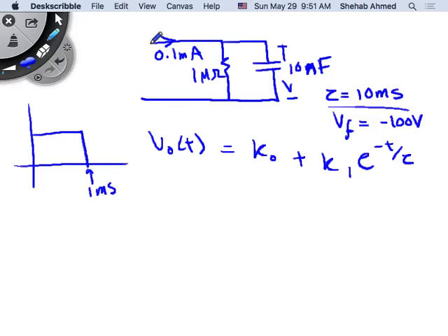Again, it's like you remember from your 214. You put a DC source here, and you put a switch, and you close the switch at t equals 0. How do you find the equation for current? Right after the switch is closed, you want to find an expression for current, and then find the corresponding output voltage developed across this capacitor. Because that is equal to the negative of the output voltage across the op-amp terminals, right?